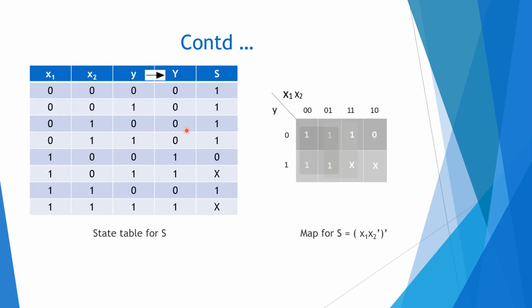and this is the equation, the state table for generating the value of S. Again we have written the same as for the NOR latch here. From the excitation table we will get these values, and according to the excitation table we will write the value of S into the K map here, to find out the value of S. Here we obtain S equal to (x1 x2 bar) the whole bar. If we deduce this expression, we will get it like this.